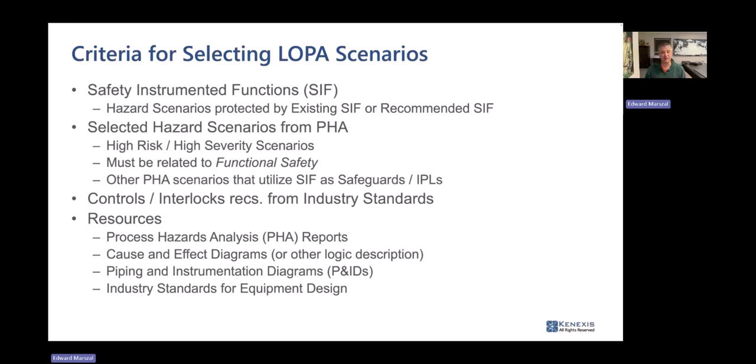So I am very, very concerned about the definition of the safety instrumented function, whereas some PSM practitioners are just generally interested in achieving a tolerable level of risk for the plant as a whole. And the safety instrumented function is just one of the ways to get there. So there's not as much care and attention in the definition of the safety instrumented functions during that phase of the process.